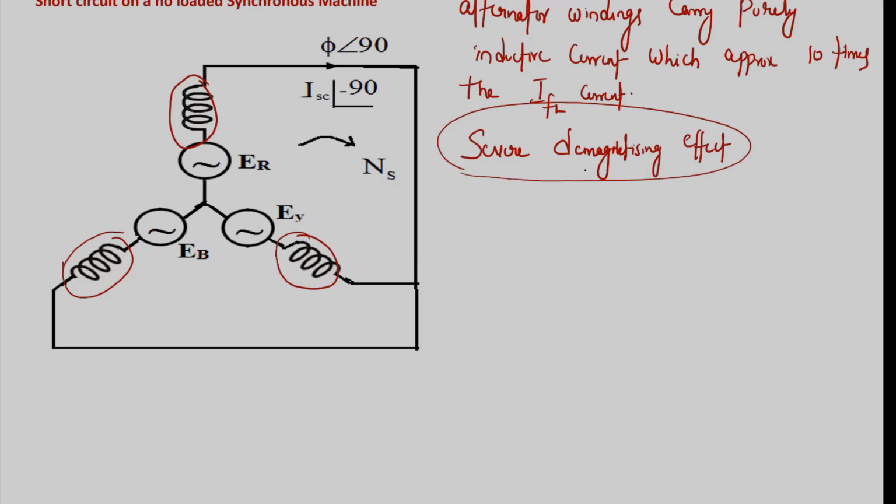Since they are acting in opposite direction, then what would have happened? The main field flux inside the air gap between stator and rotor would have become zero. Okay, but however, to keep the law of constant flux linkages, to keep the air gap flux constant for a momentary period of time, what will happen? Some DC decaying currents are induced in main field windings and damper windings.